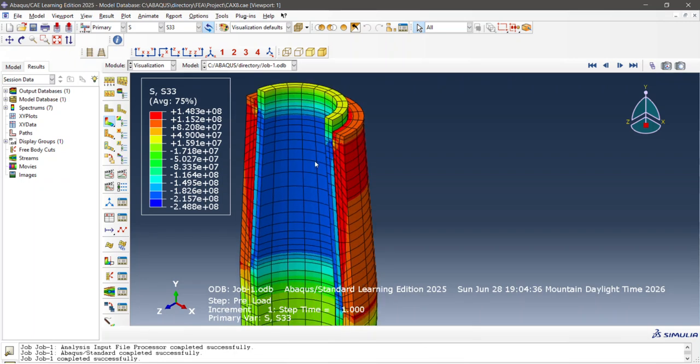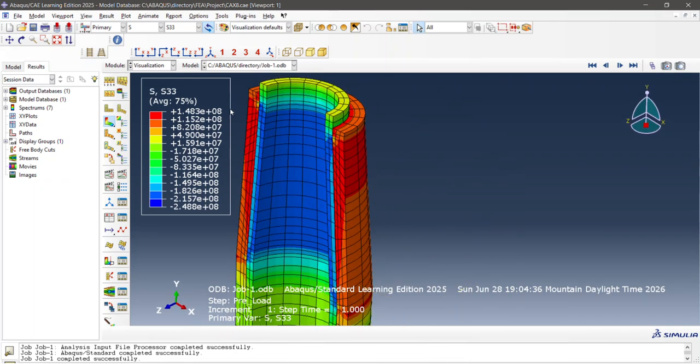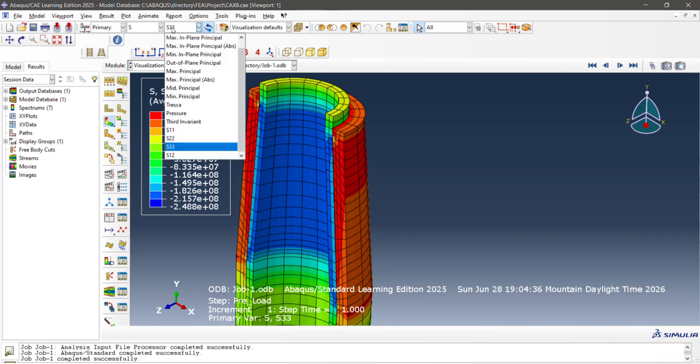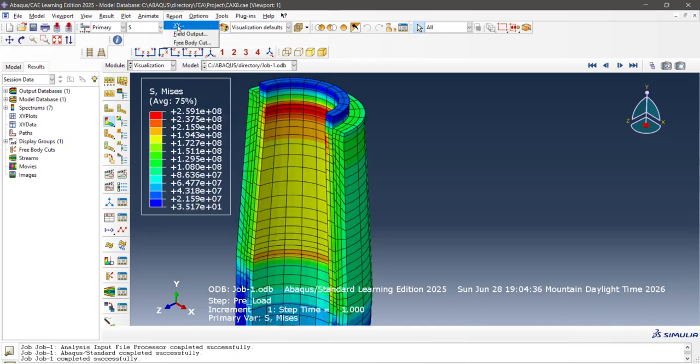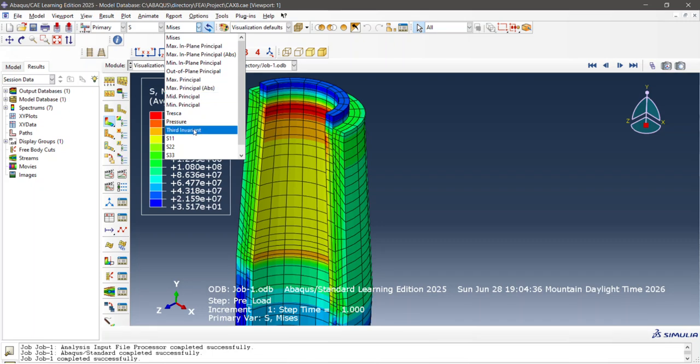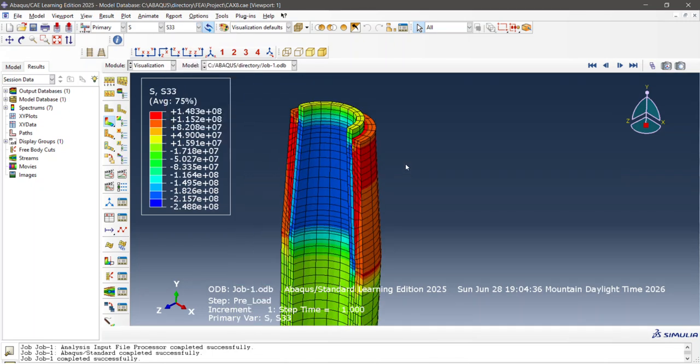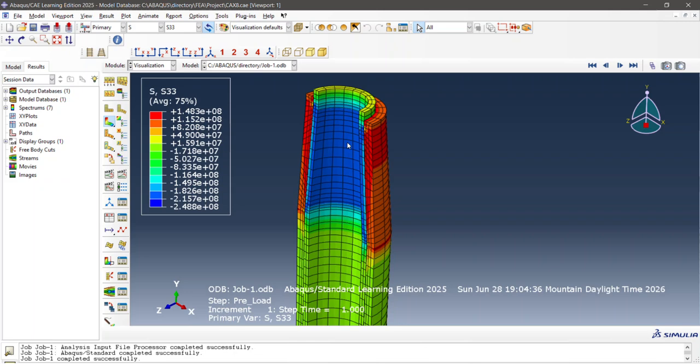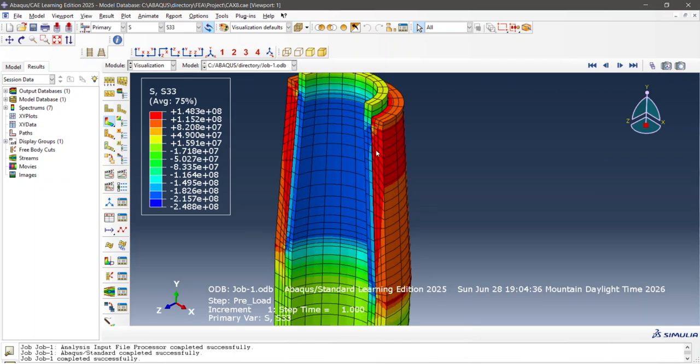So our hoop stress really doesn't change a heck of a lot, right? Yeah, all right. And our von Mises stress is also well within yield for the mast itself. The mast itself is well within its yield strength. The hub is yielding, but again, this is a scenario you would never see, and it's with material that actually isn't used on the aircraft, and the dimensions are ballpark. So for me personally, warm and fuzzy. Even I've flown on these aircraft, so that doesn't bother me at all.